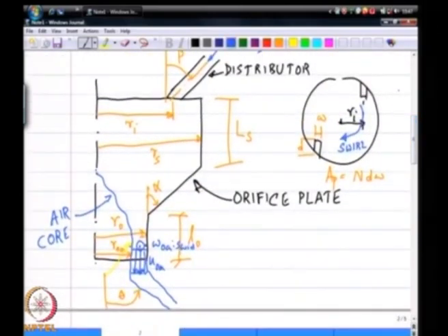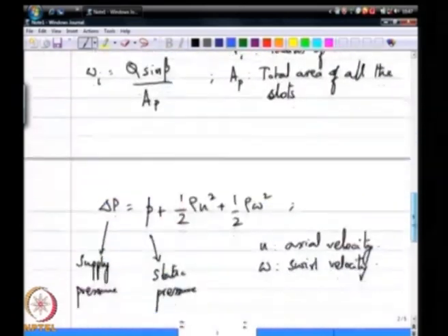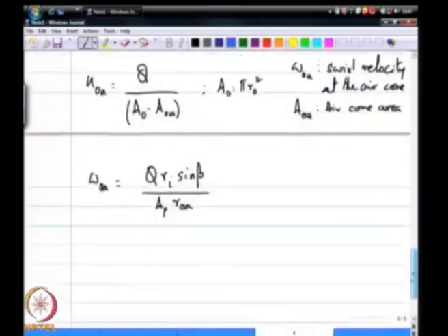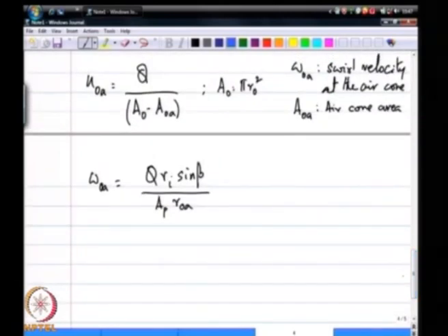So, let us make some notes here. This velocity vector has a magnitude of q over A p, and the component that is in this plane here is q over A p sin beta, and that times r I is the angular momentum essentially, times rho of course, but instead of writing rho V r, we are just going to write V r because rho is constant everywhere.